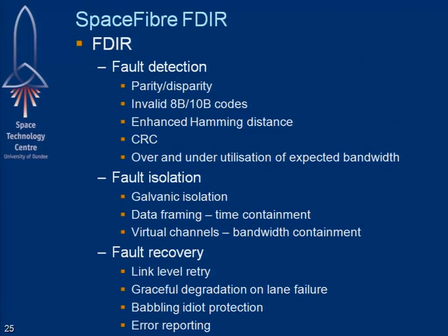Okay, so that's the quality of service. So we've got this integrated quality of service mechanism, which is integrated in hardware. It's very simple, and it provides these 3 different quality of service mechanisms. We've also, in this layer, added in the FDIR capabilities.